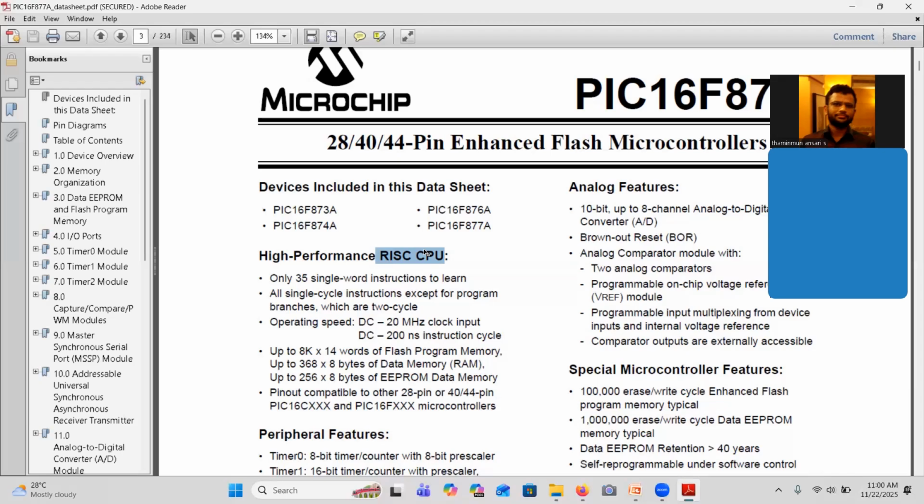But there are certain requirements. You should not operate this microcontroller below a particular frequency. Say I want to operate the microcontroller itself at 1K. That is not advisable, because you will get a lot of noise and other problems. The reason they go for high frequency is to filter out the noise. Otherwise your processing will be faulty.